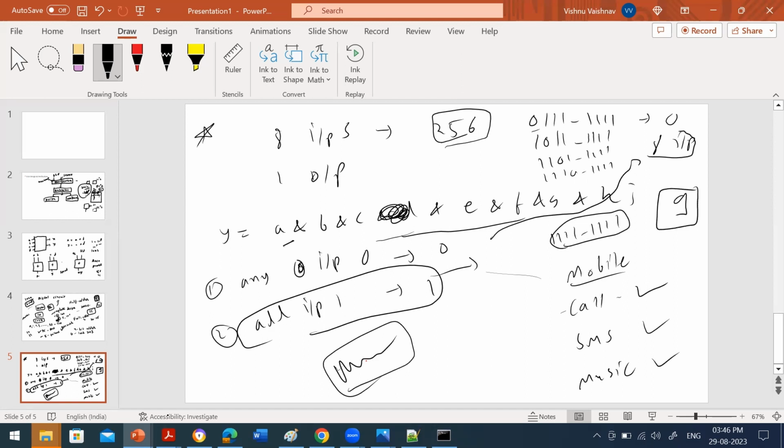See, where is your 256 and where is 9? And this 9 input, you are so confident. You can definitely say you don't have to apply 256. By just applying these 9 inputs, you can take credit of all 256. Just see, these 9 inputs have that confidence. It will make sure that your design is bug free without applying 256 inputs.